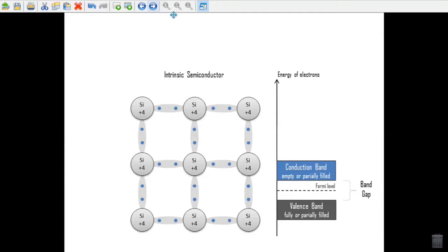Then comes the bipolar transistor, the junction transistor or the sandwich transistor, a transistor made from a sandwich of N and P type semiconductor material, either NPN or PNP. The middle section is known as the base and the other two as the collector and emitter. When used as an amplifying element, the base to emitter junction is forward biased or conducting, and the base to collector junction is reverse biased or non-conducting.